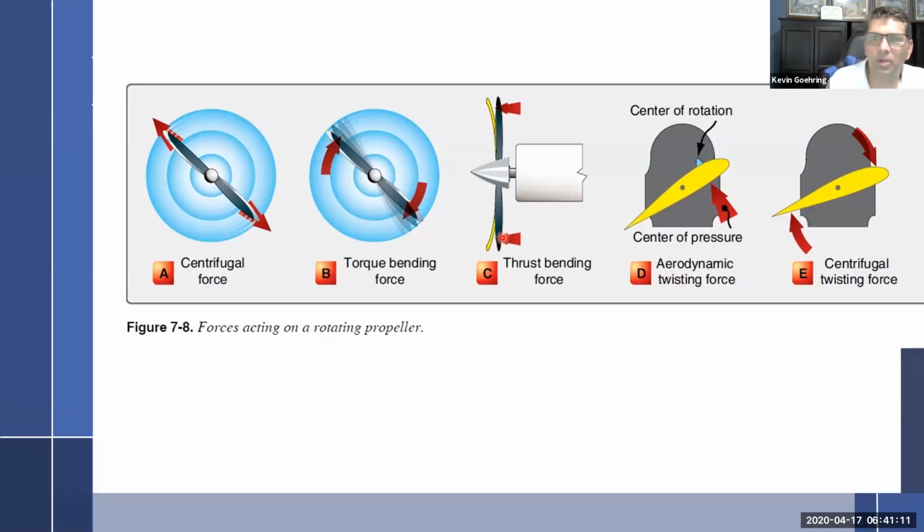While I'm looking at that, one of the things that makes me nuts, and I'm really freaked out about my airplane, is I do not like people touching my propeller at all, period, ever. People tend to grab propellers and move airplanes around with them. The theory would be, I suppose, that if the propeller's strong enough to pull the aircraft through air, it's obviously strong enough to take a few pounds of force while it's on the ground.